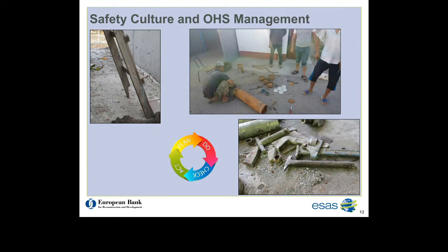The training of workers includes a basic induction with no refresher training. Workers do not understand what constitutes good international practice. High-risk activities and competent persons and authorized persons are not identified, and there is generally a lack of supervision and inspection of construction works. Compliance with requirements is left to the responsibility of subcontractors without any support from the client.